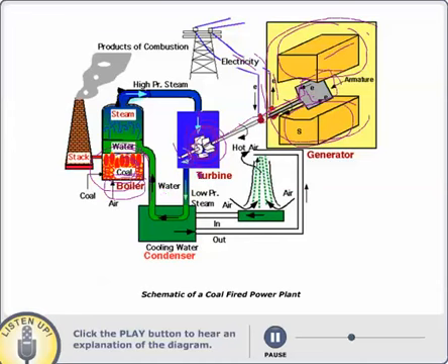Now, let's get to this turbine. After the high pressure steam turns this turbine, it converts into low pressure, low temperature steam. That steam is sent to a condenser. This is the condenser, which has cold water on the outside. When the steam is going through this cold water, this steam turns into water, or condenses. That is the reason we call this a condenser. And this low pressure steam that is condensed into water is put back into the boiler, which again turns into steam.